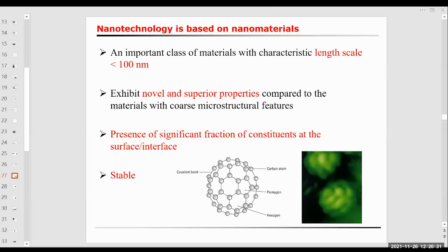All the powder particles are now put together, and then a piece of iron has been made. You put this piece of iron under a microscope and observe, you will see more or less the same arrangement of atoms within the sub regions or sub volumes. But in the case of the solid iron piece, you no more use the word crystallite to explain the small crystalline volumes within that solid. In the case of a solid iron piece, you use the word grain.